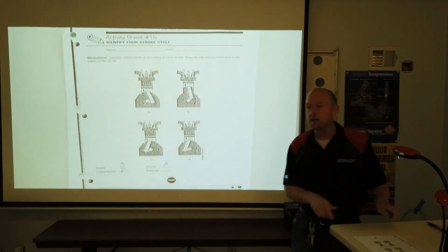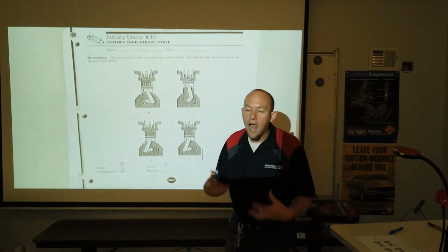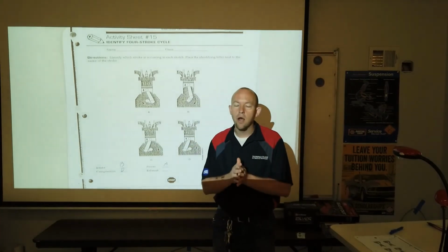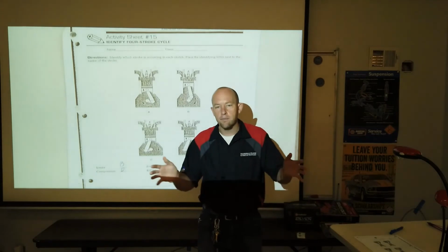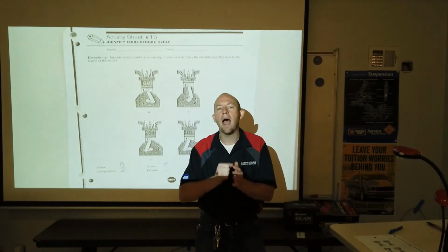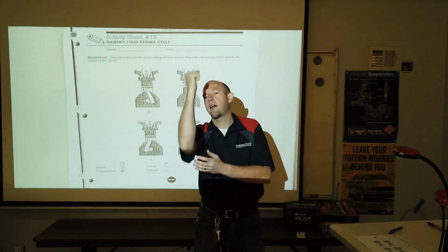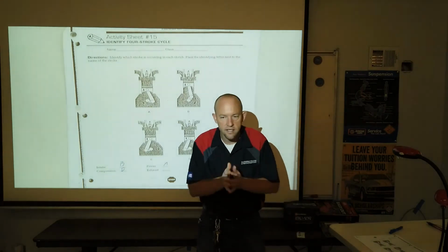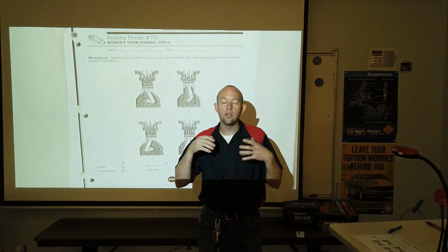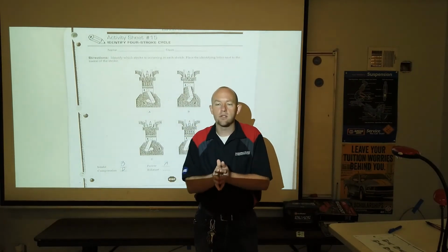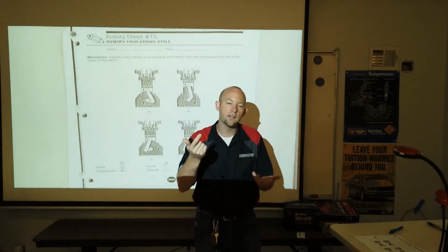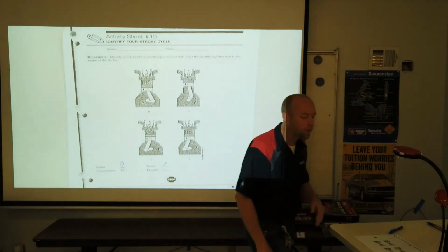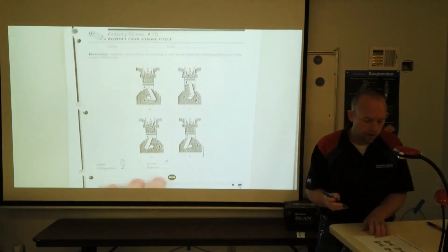The reality is that the spark actually occurs on the compression stroke on all of these engines, and the reason for that is fuel takes time to burn. We want maximum pressure on the piston just after it peaks over on the power stroke. Since it takes time for fuel to burn, usually we lead it and start lighting off that air-fuel mixture a little bit before, and therefore spark would occur on the compression stroke.